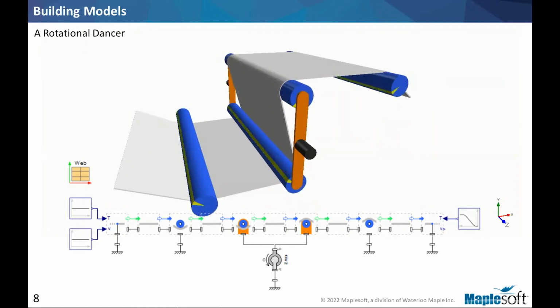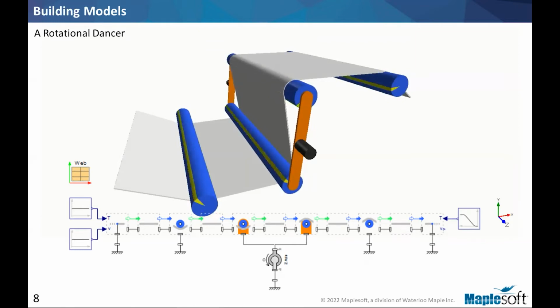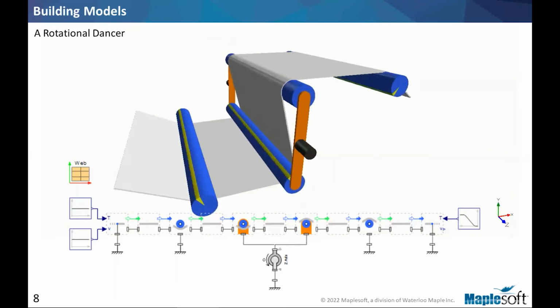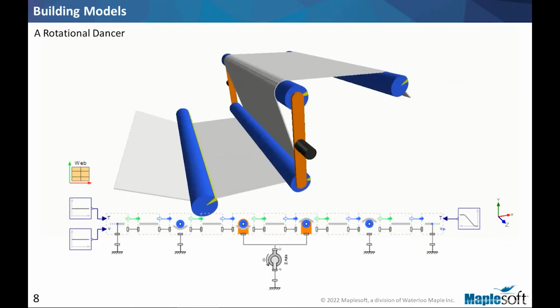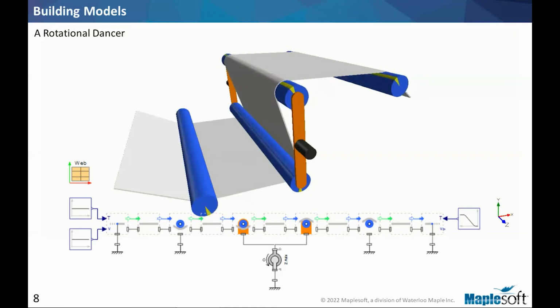We actually, with that, as the shape of that icon shows, it's a ramp. So we are gradually increasing the tension of the downstream. And you can see that effect of that tension increase in the rotation of the dancer arm, because that dancer arm is under spring load. This potentially can be used in a variety of scenarios, like feedback for tension regulation. I will show an example of that with a different type of dancer a little bit later on.